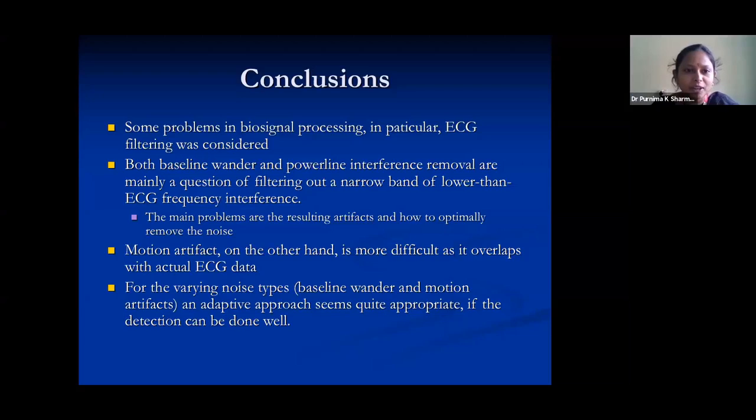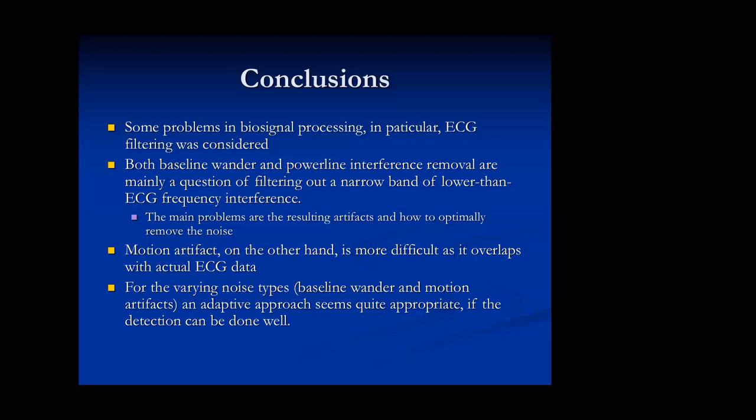Any doubts from the participant side? Sir, one more doubt in the chat box, sir. Artifacts due to power supply? Yeah, that I have discussed now. We can remove them using a notch filter. It's basically 50 Hz only. I have to reject only the 50 Hz signal. I can design a narrow band reject filter which can reject only a single frequency, 50 Hz.